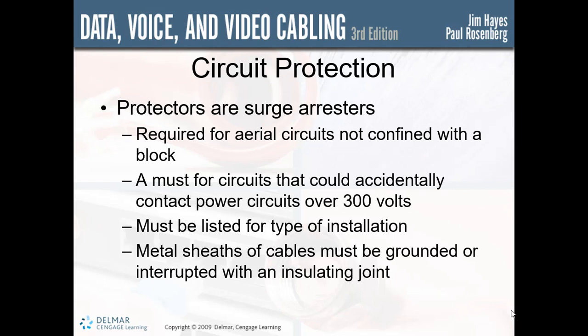If there is a grounding conductor, it must be run as directly as possible to the grounding electrode, and it must be protected if necessary. If the grounding conductor is protected by a metal raceway, then it must be bonded to the grounding conductor on both ends.